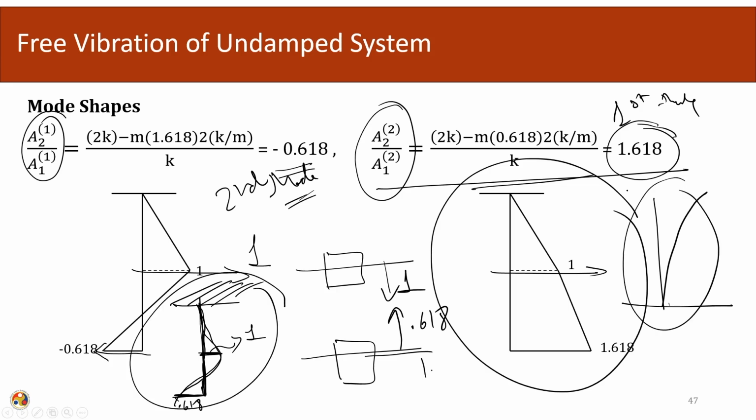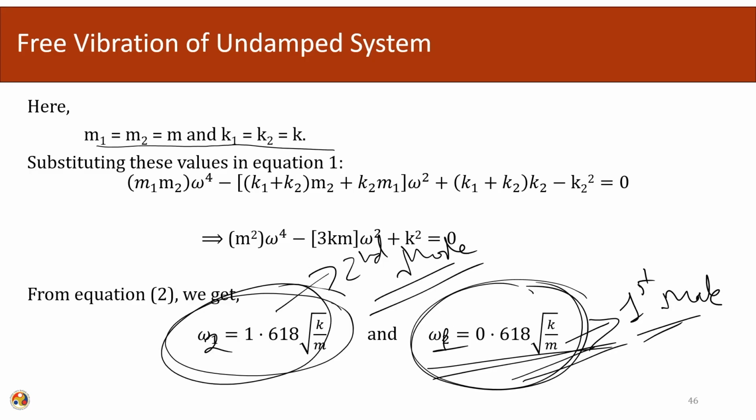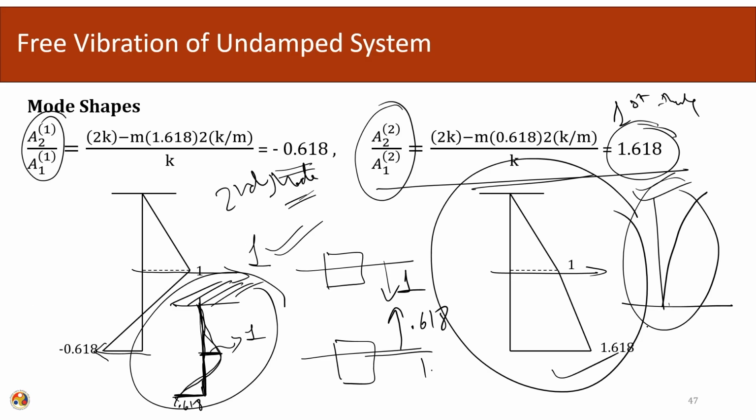It means that this lumped mass approximation agrees with our established criteria of the mode shape of the cantilever beams. Okay. So, in this way we can check the validity of our solution, as we compare it back to our established mode shapes. Okay. So, what we have done here till now is that we have calculated the frequencies and we have established the mode shapes for the two frequencies.